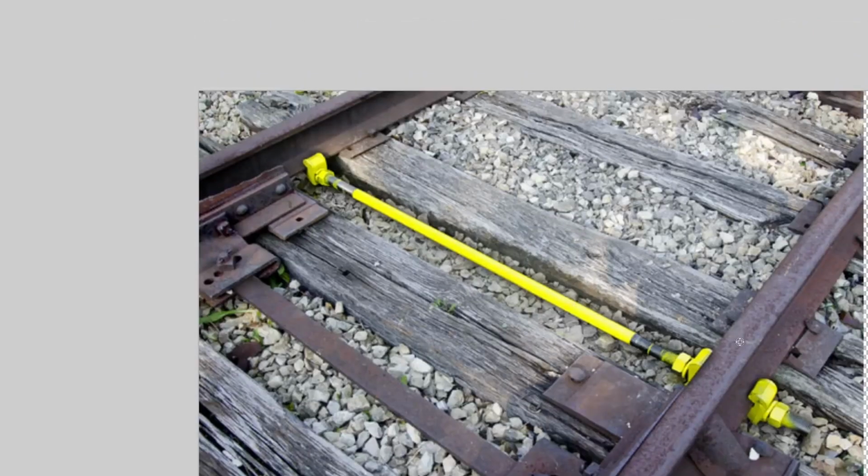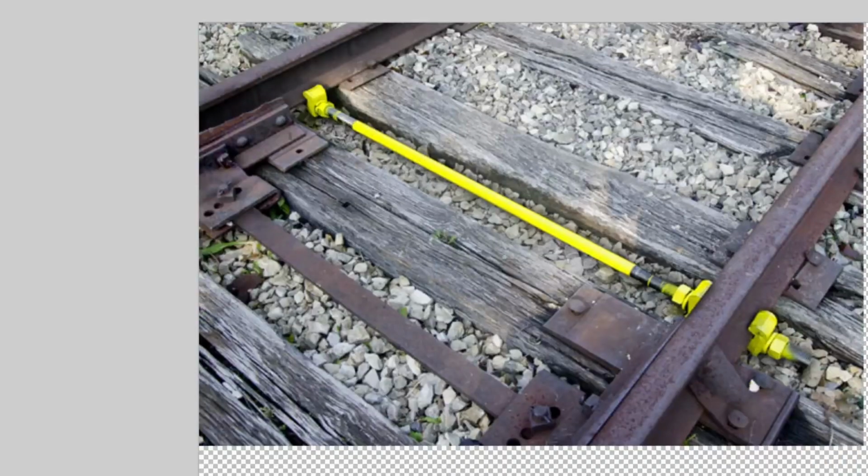And one last important thing to talk about as far as holding the rails together is something called a gauge bar. And this is a gauge bar. It is a metal bar with threaded rod ends that can be adjusted to put it in place and then grab both sides of the rail. And these can help hold the rail to a precise gauge, because things can work, and as you can see with some of these ties looking a little sad and worn out, a gauge bar in this instance can help hold the rails to the right distance apart so that our trains can run across them. And it's a good way to keep things in check along your railroad.